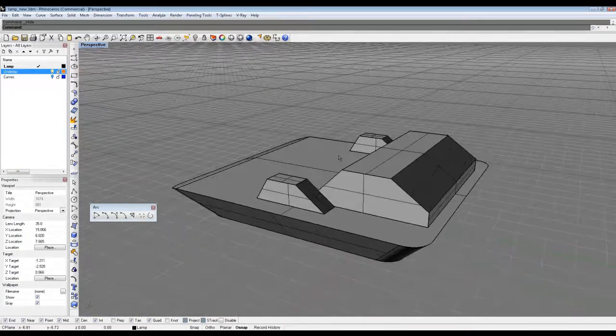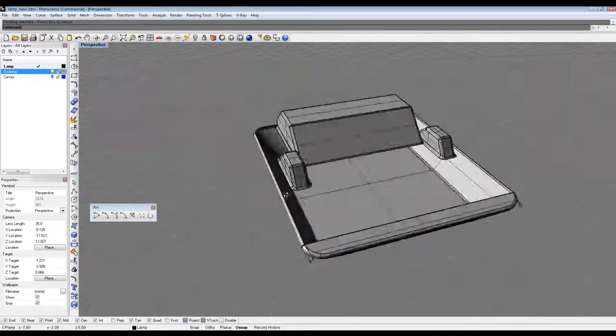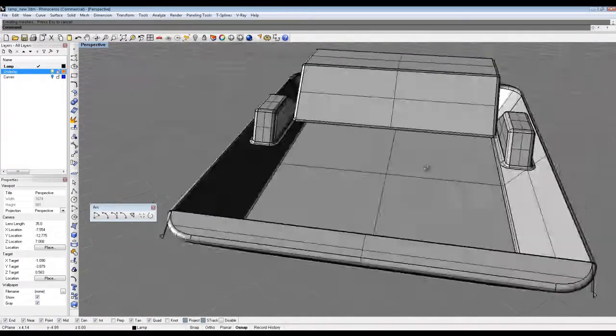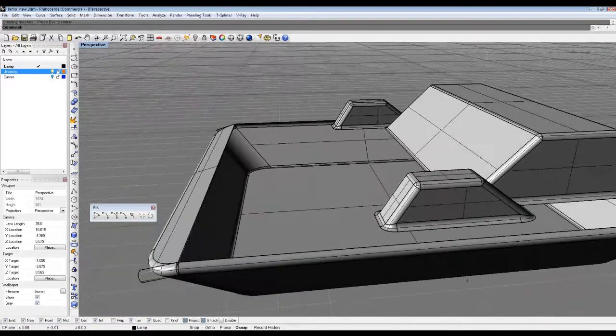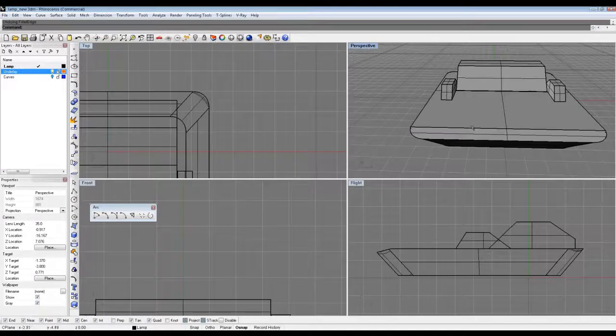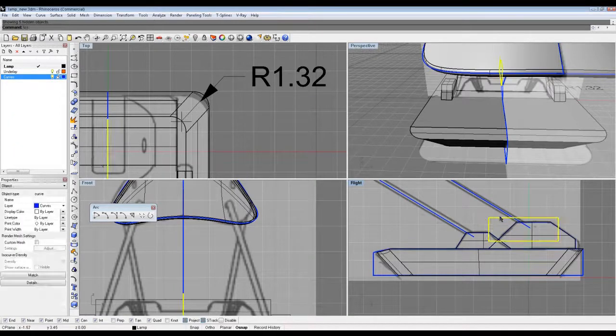Now I'm going to invert everything and hide it, and then put some fillets back into this. So fillet edge and 0.12 I believe worked. And this is the other really cool thing about the fillet command, you get a really nice result, as you can see, except for the face had gone off here. Let's see what the issue is. Sometimes if your fillet's too big, you'll get a lot of crossing faces, such as right there. So what I might do is actually, oh, you know what? We forgot one quick little thing here, and that is we need to extrude out this little guy too.